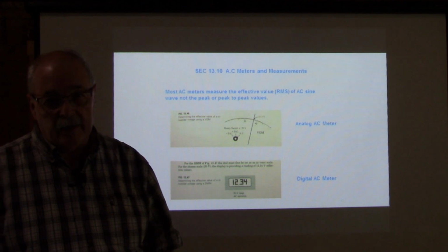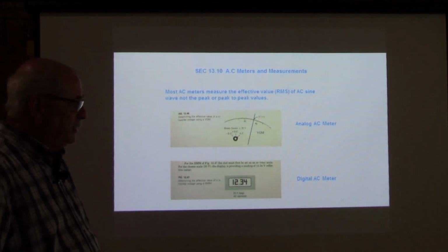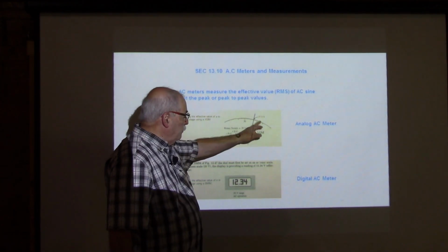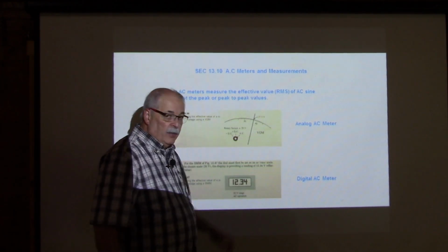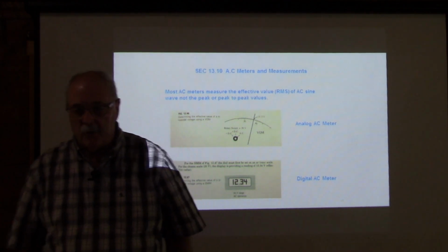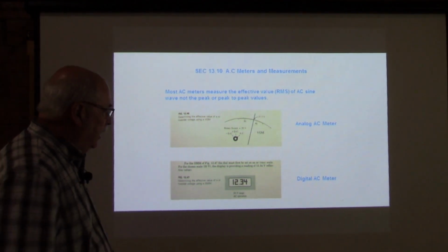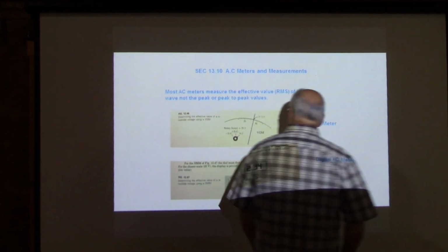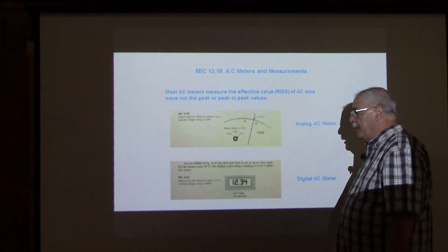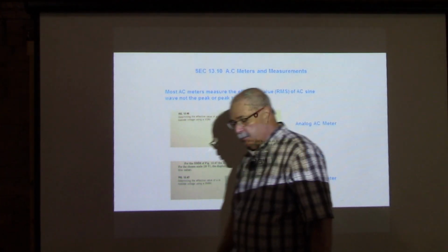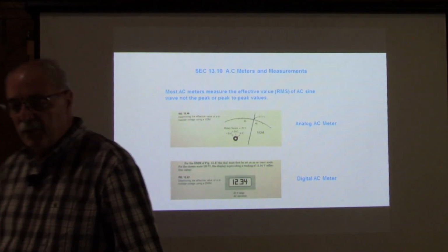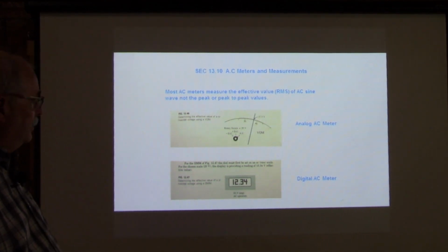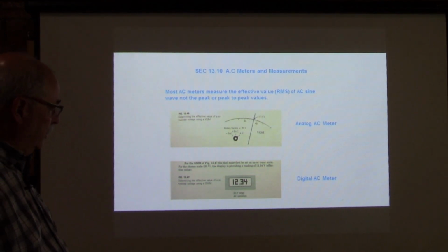What it does do is take away interpretation. So looking at a needle against a scale, right, it's halfway between here and there, and something called parallax, that if you look at a meter this way, it has a different reading than if you look at it this way. All right, keep that in mind on analog meters. Something called parallax, you're supposed to look pretty much dead on to the needle and where it sits, but it doesn't necessarily mean it's less accurate than the digital meter.